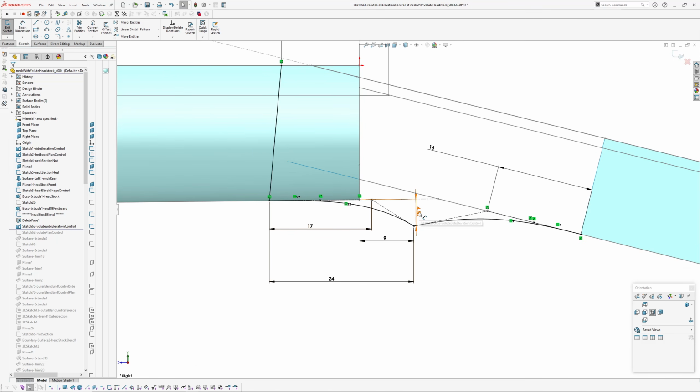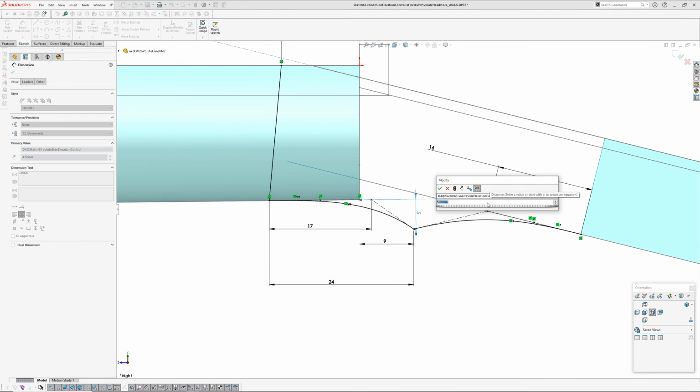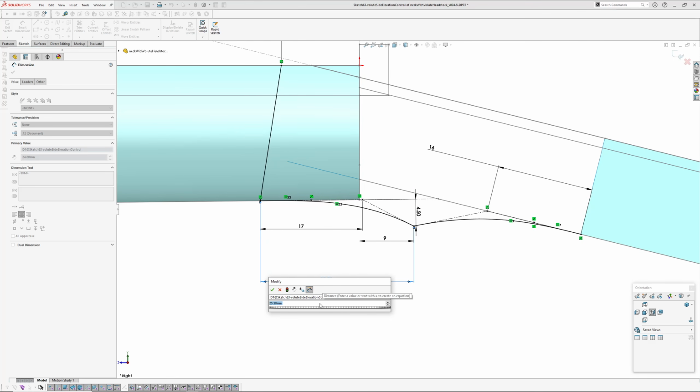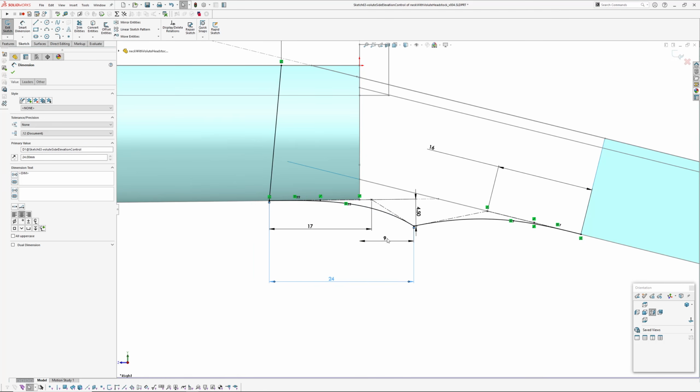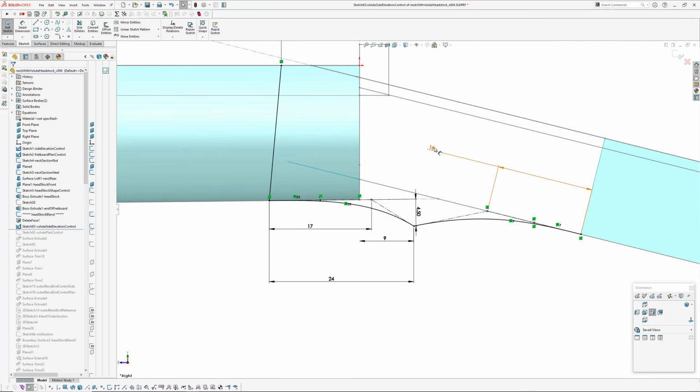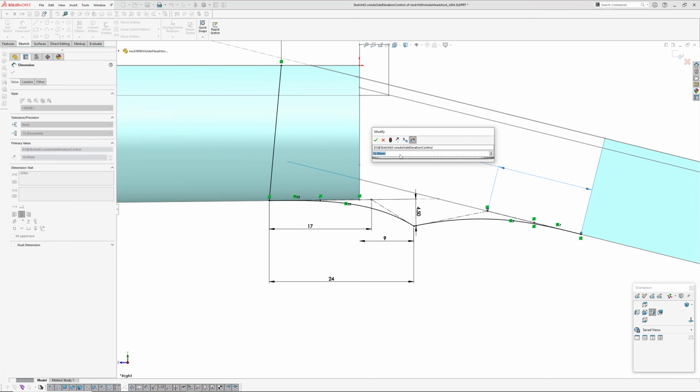And then I've got dimensional control over the height of the volute, like the length of this blend. If you want to offset the volute, make a slower run into it, and also the volute's position in relation to the nut. My origin's at the nut there, so you can shift that whole lot around. And the other thing is you can control how tight you want the curvature running into the volute.